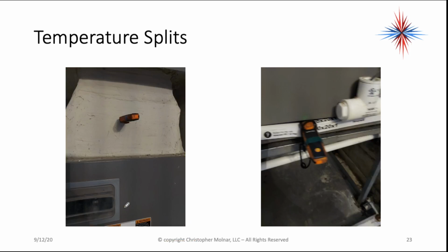Next thing you're going to do, you're going to put the front of the unit back on. You can see here I have the front of the unit back on. Okay, I've put a temperature probe into the supply duct, and we don't have a return duct on this system. It's up on a stand and the air goes basically in this way. So I put a temp probe over the filter just as a place to put it. Okay, and it's not going to be perfect, but it will capture the majority of the temperature of the air going across that filter. And I made sure I got it in far enough. The probe is actually going in far enough to not catch the bottom of that coil, okay, because I need to have it past the drain pan and actually in the airstream.